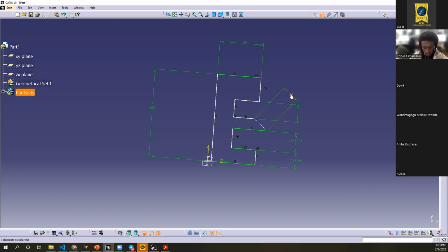And one thing I forgot to tell you is you have to make sure whenever this happens, this means that you're dimensioning the points, and you have to make sure that the line is horizontal, right? So if this happens, just press the escape key, click this, delete this, and just press control plus Z, and then just take this out a little bit.